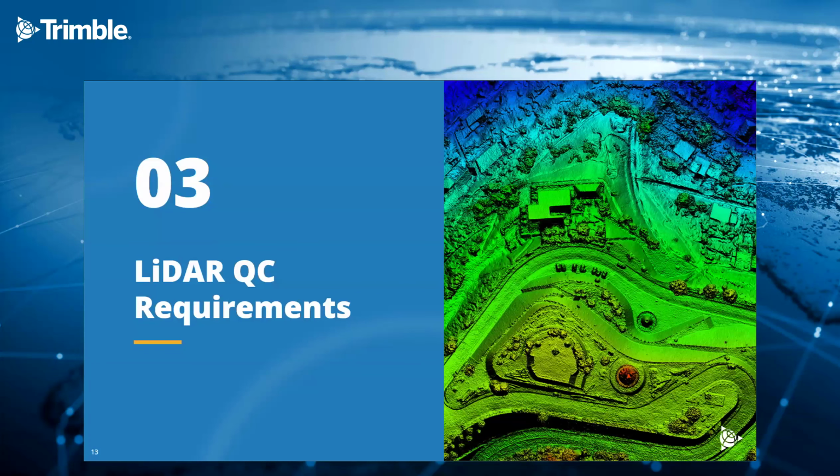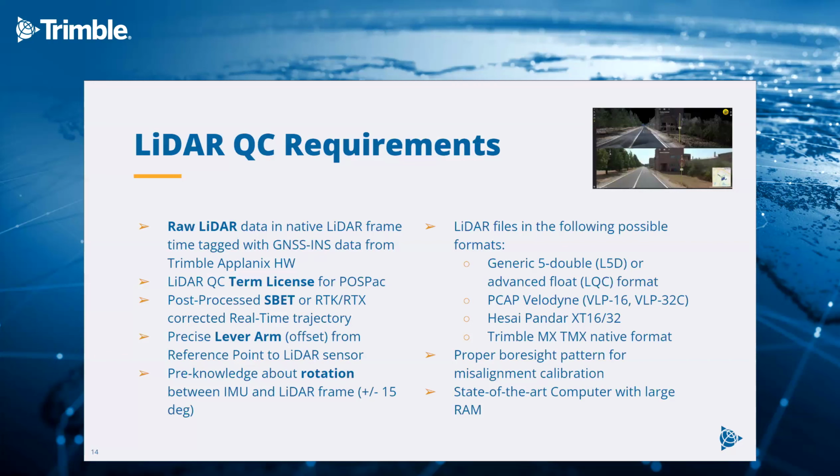Okay, that brings me to LiDAR QC requirements. First of all, of course, you would need to have the raw LiDAR data, and those data need to be available in the native LiDAR frame, time tagged with the GNSS INS data from the Trimble Applanix hardware. That's quite important.